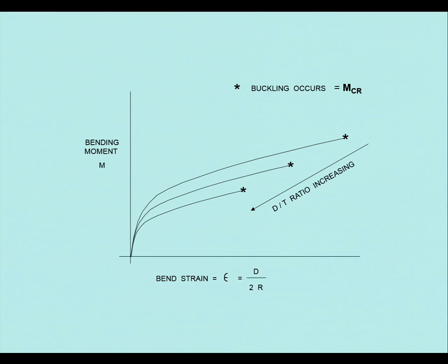So, what is the structural difference between bending and buckling? Well, if you've got no pressure, you'll get pure bend, collapse due to bending. And if you've got pressure but no bending, you'll fail due to pure collapse. But that situation will never arise, because you'll always have, like here, when you're laying, pressure and bending. So you've got to be able to combine them.